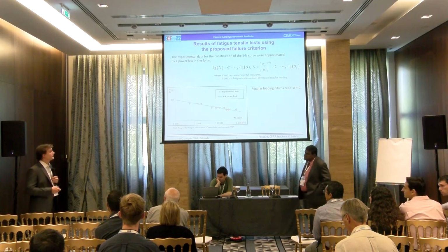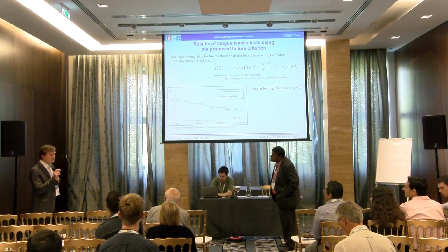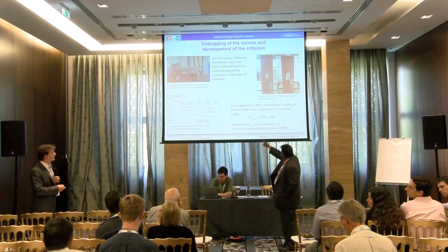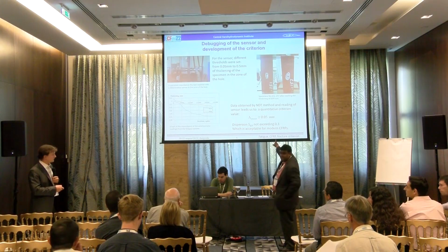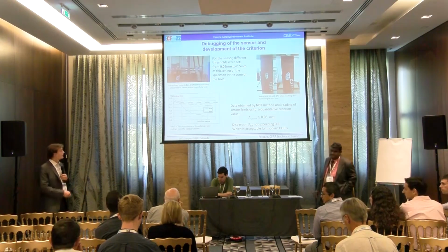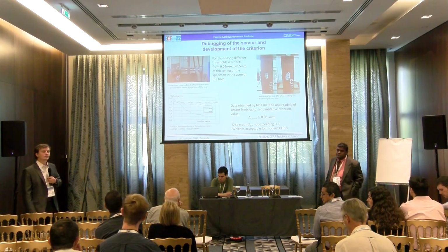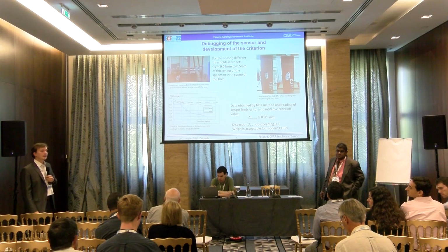We take as a failure criterion the value of the change of thickness of the specimen around the hole by this value. At what change do you consider this failure? When it's equal to half a millimeter? 0.05 millimeter, yes. And that you consider failure? Yes. Actually, if you have a structure with a hole in it, and you have this change of thickness, it can still carry load. So yes.